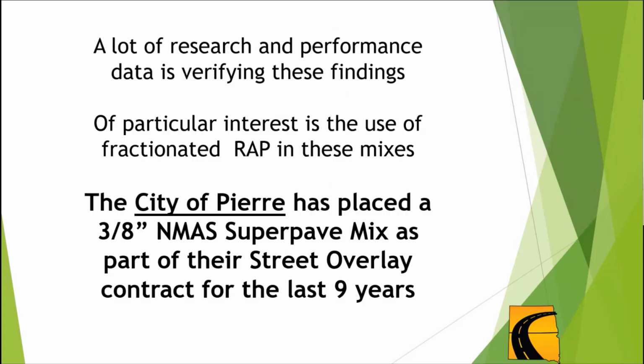I bring that up. I'm sitting here in Pierre, but been in Pierre for 20 years now. Worked a lot early on with their staff for almost 10 years now. They've been using 9.5 millimeter, actually a 6.3 millimeter super pave mix for all their street overlays. And in some cases, they don't even have to come out with a grinder and do curb reveals, so that you can taper them in.